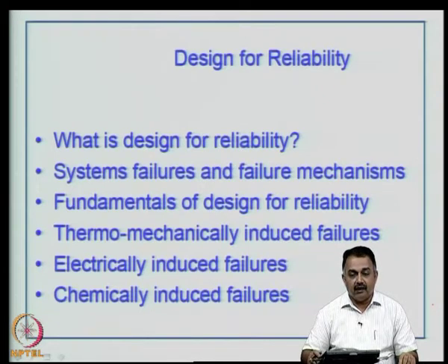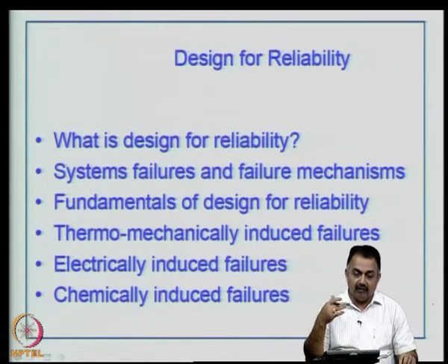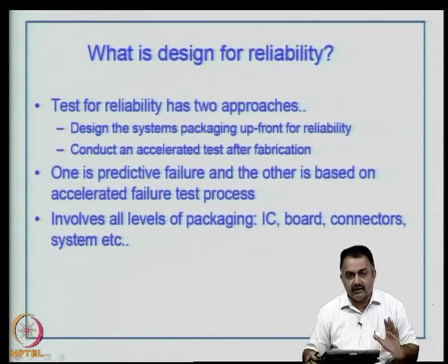Fundamentals of design for reliability: you need to understand most failures are thermomechanically induced failures. There can be electrically induced failures and chemically induced failures, but all failures, whether chemically induced or mechanically induced, will end up as an electrical failure, right. So, test for reliability has got two approaches. Design the system's packaging upfront for reliability. So, look at these considerations.